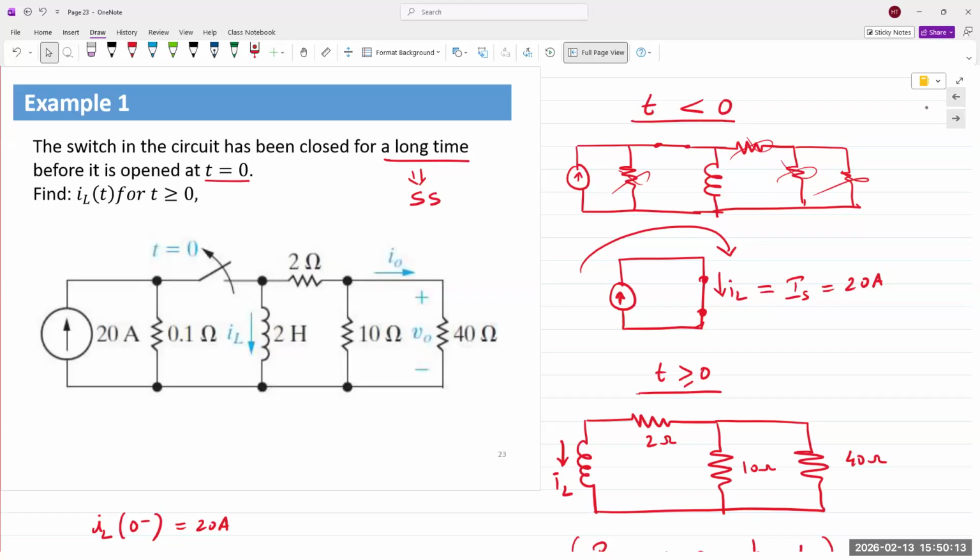That filtering capacitor is used so that it smooths out the AC waveforms, right? A diode first rectifies it from positive and negative to positive only, and then it passes through a capacitor, which flattens out the response. The way it works is when a positive cycle arrives, the capacitor charges.